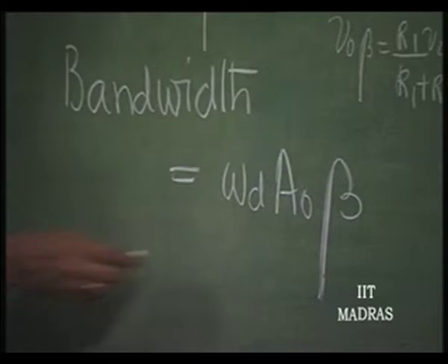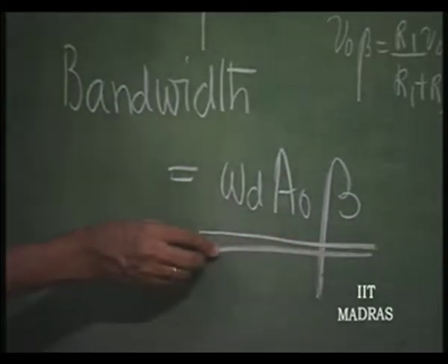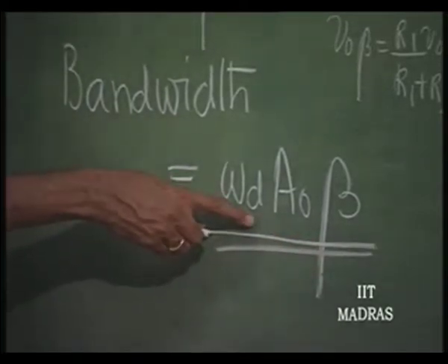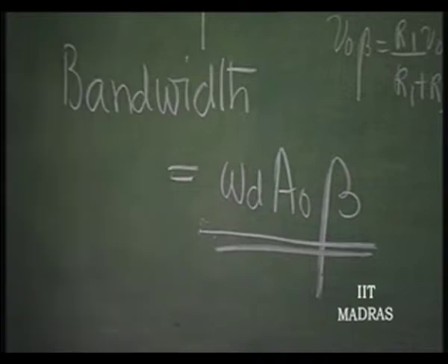So, this is an important aspect. The bandwidth of this amplifier after negative feedback has improved by a factor of A naught into beta.